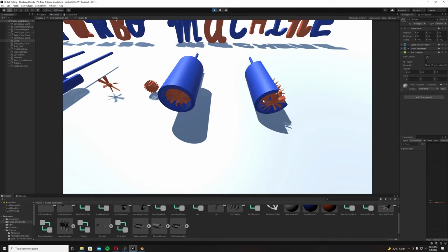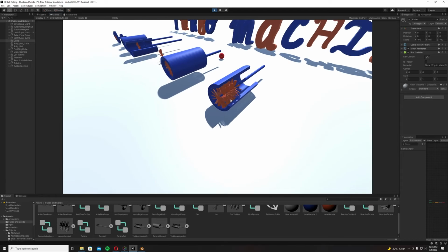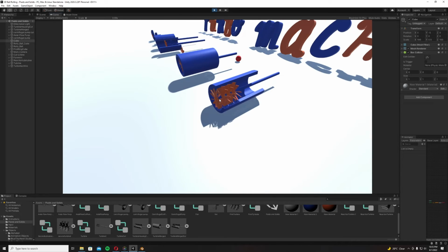And on the other hand, you have reaction turbines. This is a reaction turbine, and this is an open section so you can see what's going on. Reaction turbines utilize the pressure gradient as the fluid expands through the blades as the means to produce energy. The turbines have alternating asymmetrical blades, so that as the fluid expands as it passes through, it will spin the turbine blades, leading to an overall decrease in pressure at the outlet of the turbine and an increase in the velocity of the fluid.